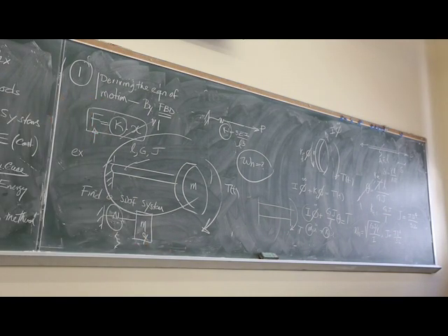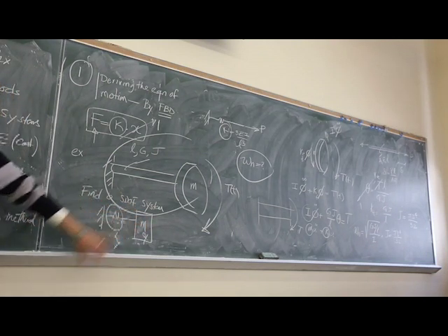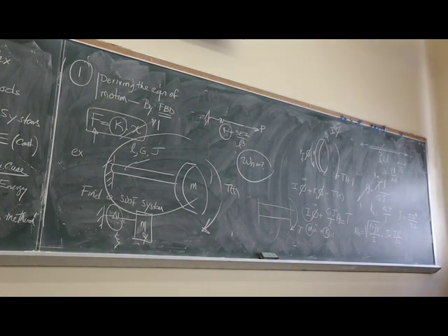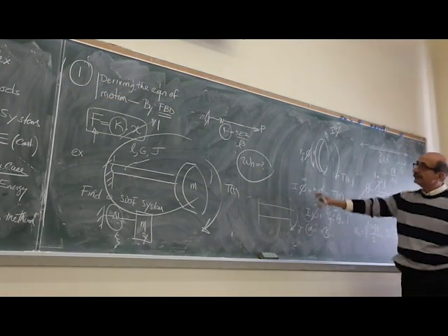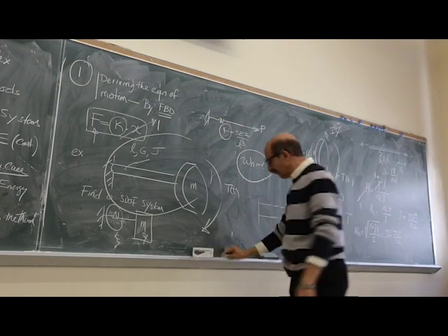Any other questions? Yes? How would you model the torsional case with springs? Yeah, this is it. Same thing. The purpose of modeling is to define M and K, because M and K are what comes in this expression, omega n. Where do I have it? I do, right?